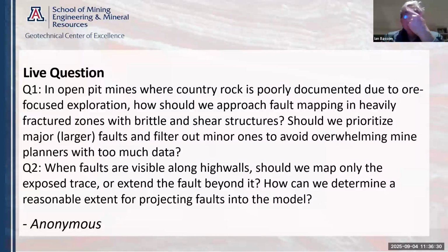I don't mind. I mean, Wayne will back me up on this, but fault mapping is obviously determining a collection of features that denote a zone of weakness or displacement, right? So the question is, what is that bag of features that tell you something major is happening? It's offset of your stratigraphy. It's fabric embrittlement. It's alteration. It's dilation. It's apertures, etc. There's a whole bag of them.